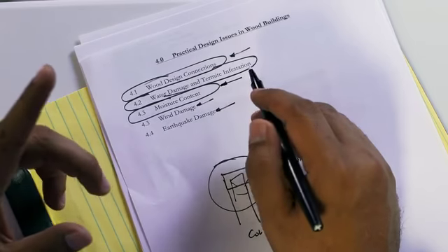So, as a precursor, just to give you a little introduction, we'll talk more about wind damage and earthquake damage in another class, but I wanted to illustrate for you the problems with moisture, water damage, and termites, and specifically give you some basic introduction on wood design and how these three elements interact with each other: beams, columns, and shear walls.